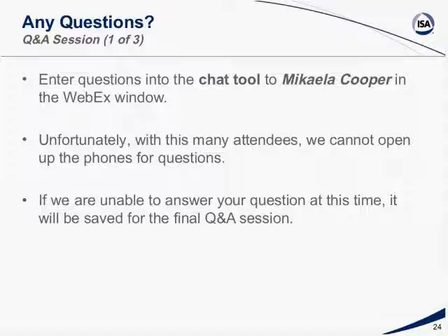Now, having said that, you still want to record that information because for troubleshooting purposes, you want to know what shut the facility down during the off hours. So you still want the good alarms. The alarm practices that we talk about still apply, but in this case, if something is unmanned, it's more for troubleshooting and diagnostic purposes than actual operator action. I hope I answered the question, Edwin. That's kind of an unusual one where you have something that's really unmanned.